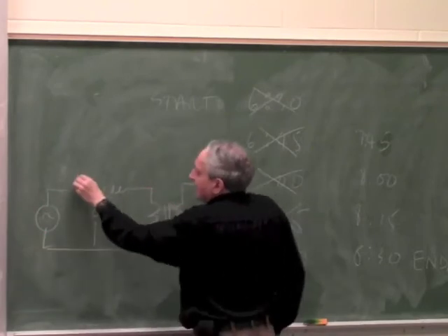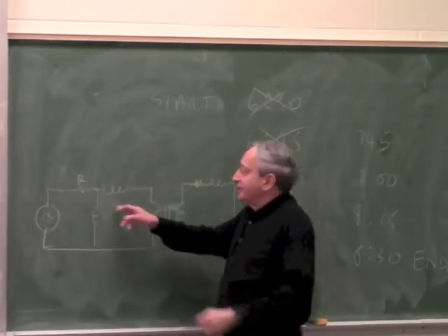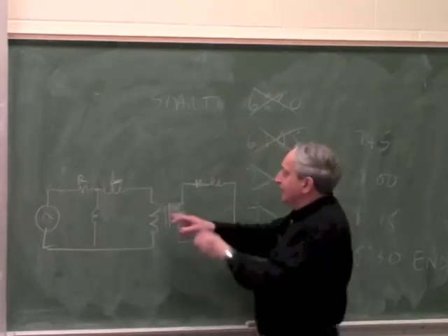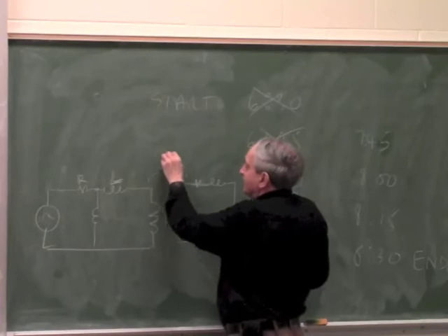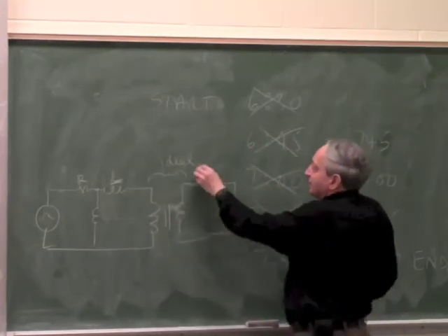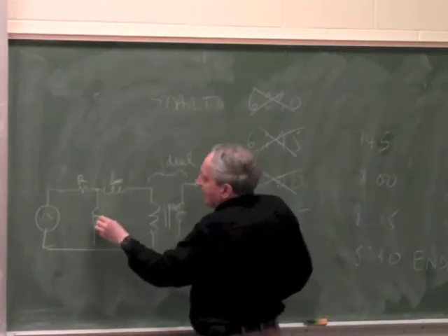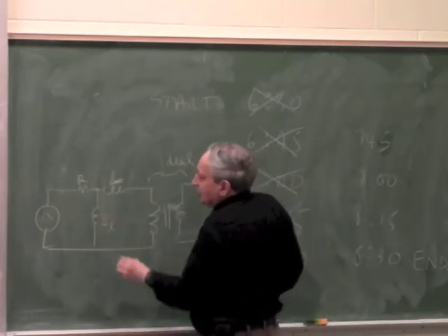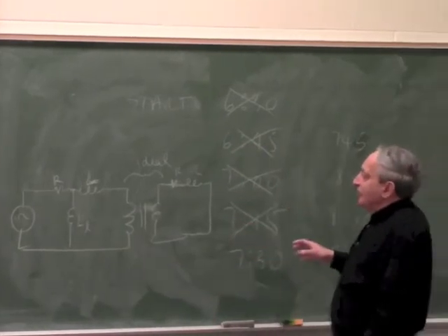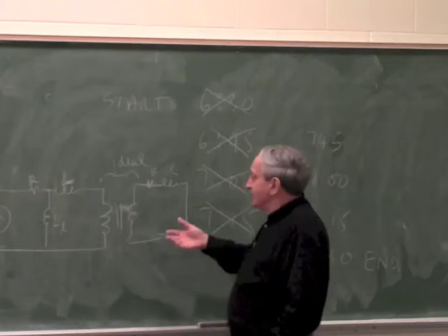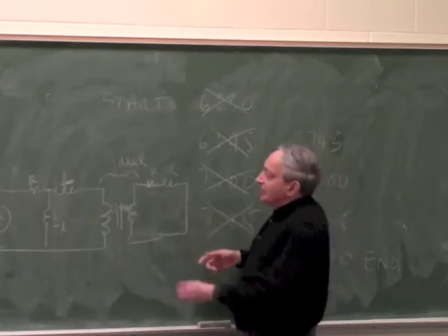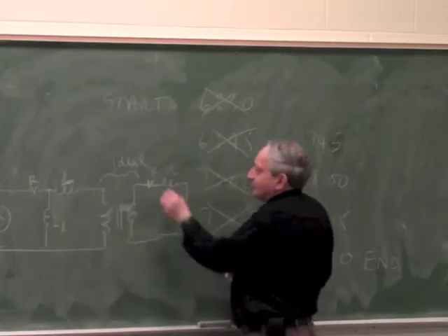This is the R, which is understood. This is L, which is the inductance of the coils. And this is an ideal transformer. This part is an ideal transformer which has no losses, no R, no anything. And again, this is R, this is L. This is L leakage inductance. So when you look at the model of a transformer, if you increase the frequency, this current not necessarily gets higher.